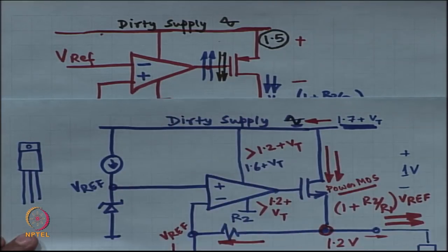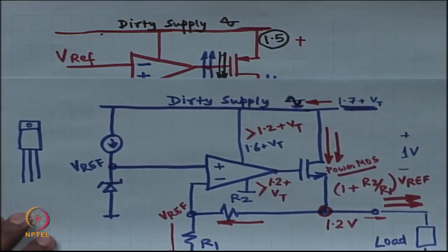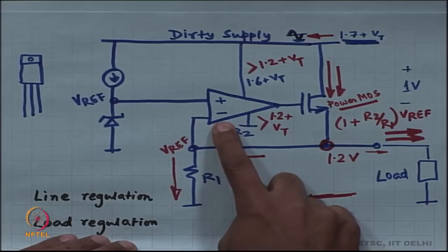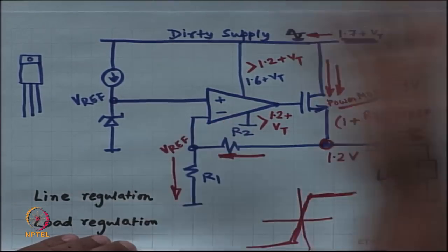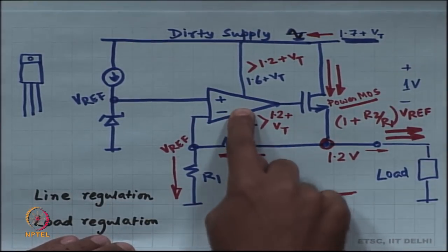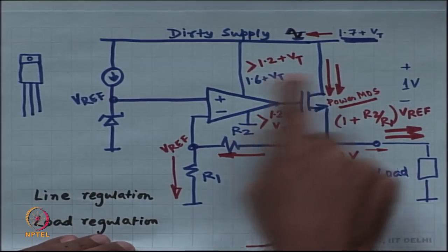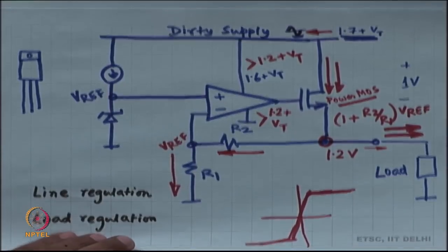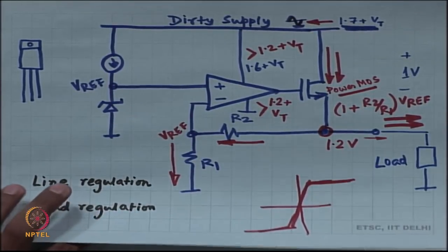Well, one thing that you can directly observe over here is that if this is a 2-pole system, this op amp is going to be 2 stages, it is going to be 2 poles, but this is just a buffer and hopefully it is not going to create yet another low frequency pole.